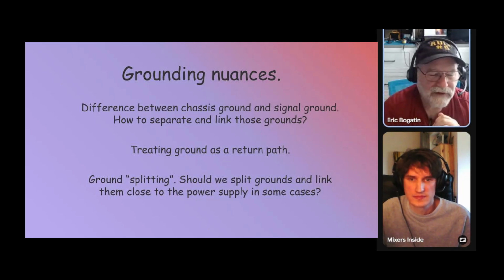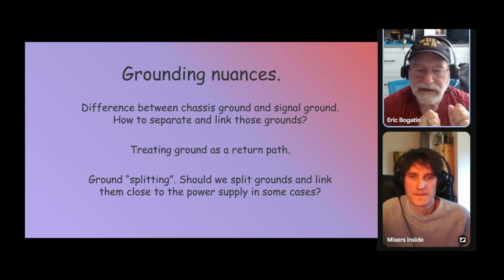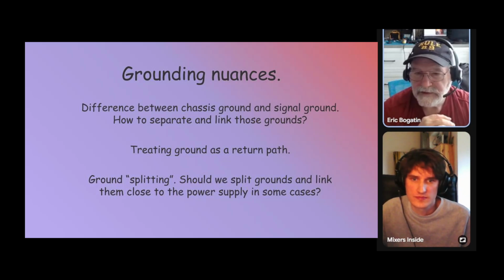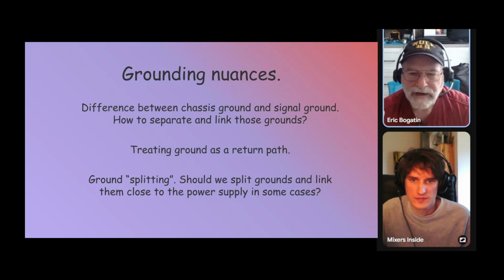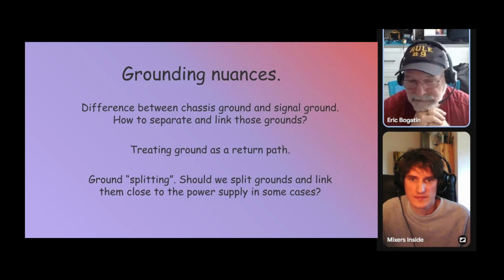I do a lot of work with biomedical instrumentation, where again, it's low-level signals that we're looking at. There, differential signaling is really important, because that differential signal is basically the voltage difference at the input of the sensor, and we carry the reference of that sensor all the way back to the amplifier as a differential amplifier. And so thinking about audio signals as differential signals, where the separate interconnect provides the local reference, helps to reduce the sources of noise. Okay, I see.